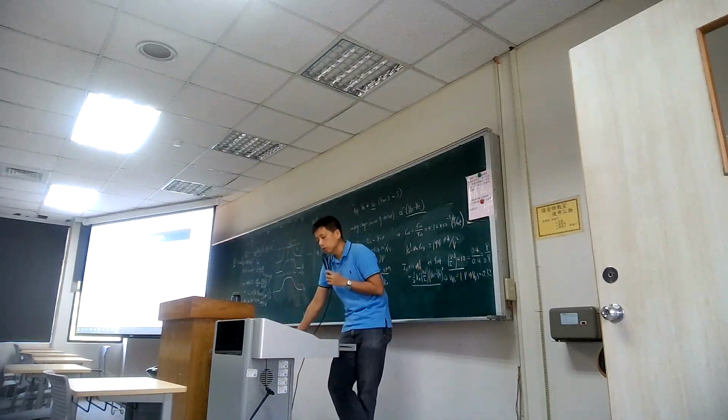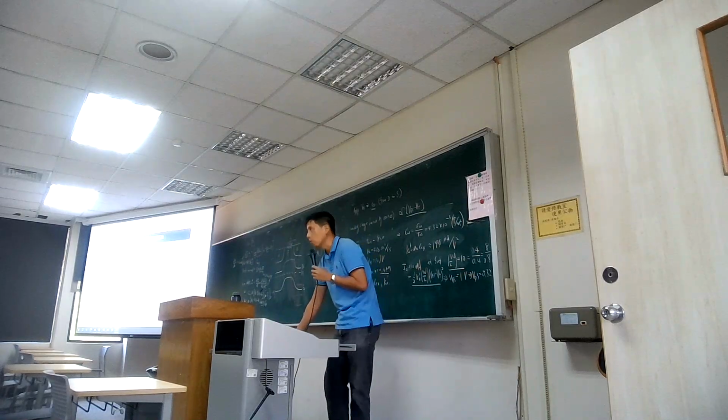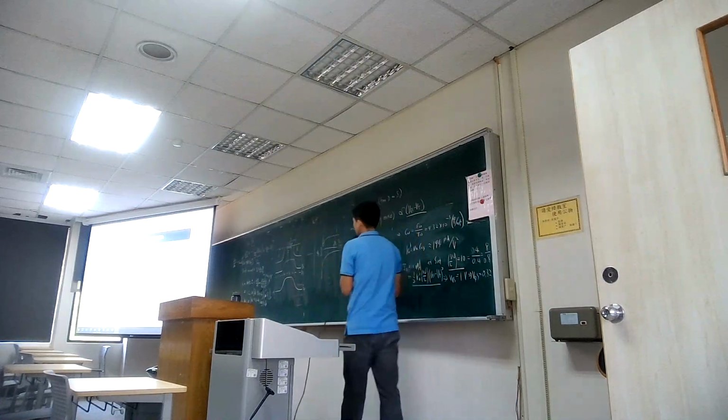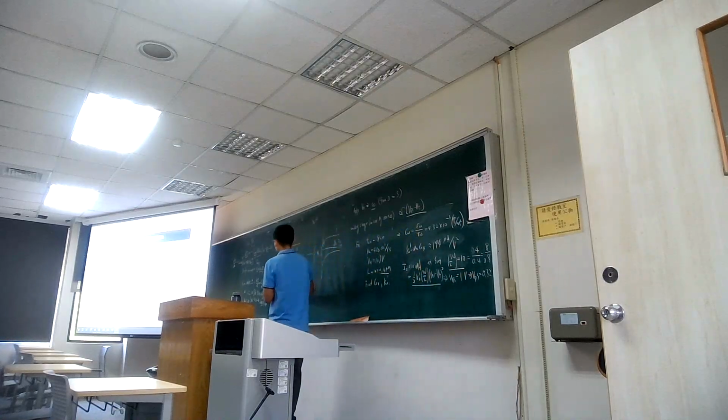So there will be an assumption that the majority carrier quasi-Fermi level, EFP, is still the same. Remember that we talked about the quasi-Fermi level of the majority carrier before. So for the majority carrier, the N-type doping and the P-type are still staying the same way, corresponding to the conduction and the valence band.